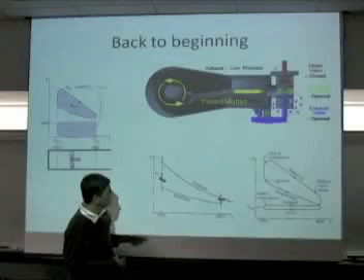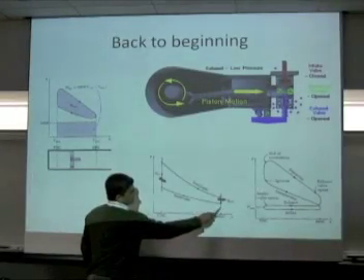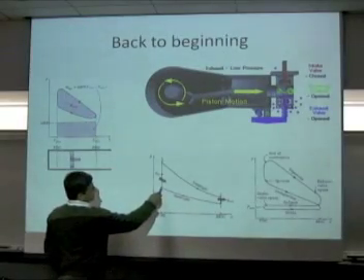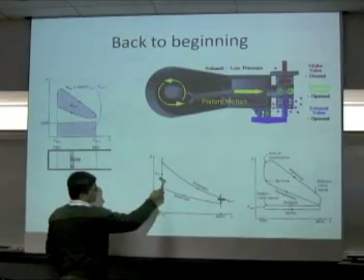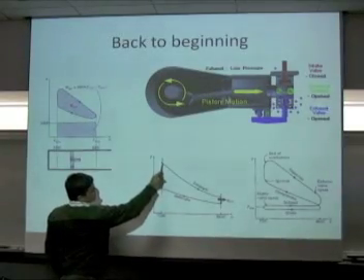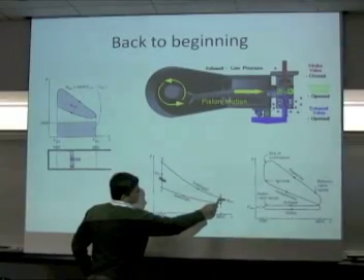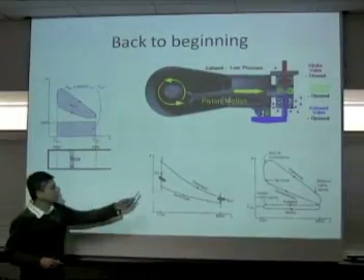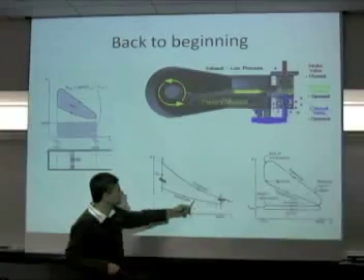If you look at breaking it down into simpler aspects, we start at 1, which is where the bottom dead center is, and then it is isentropically compressed to top dead center. Then you add the fuel-air mixture and ignite it, and you get the high-temperature, high-pressure air here, which expands further down isentropically, reaches 4, and then it's exhausted, and you lose the heat through the exhaust. It's called a closed cycle because we assume that the air that's coming out is recycled back at low temperature.